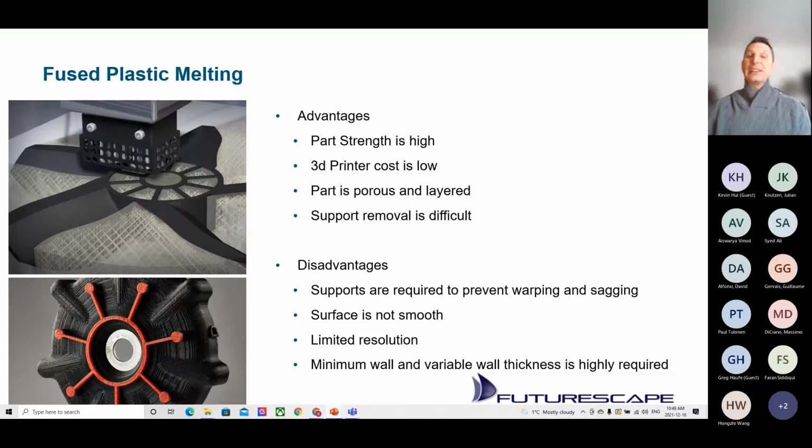The surface is really nice. I like the surface finish of FDM. It's actually quite smooth, but it is stratified. If you look at the bottom left part, you'll see there are little lines all over the place. Because the resolution is not as high and you're going layer by layer, this part can sometimes have a bit of a stratified look, like the fibers inside of a tree or wood. So it has that wood look and feel. It's not perfectly smooth, but I really like the finish because of the actual plastic melting, it has a nicer surface finish.